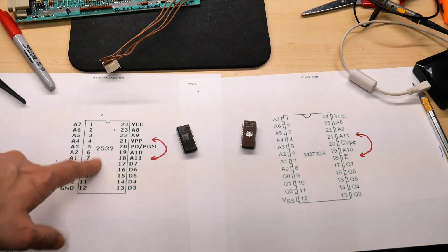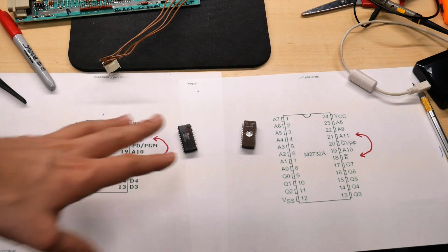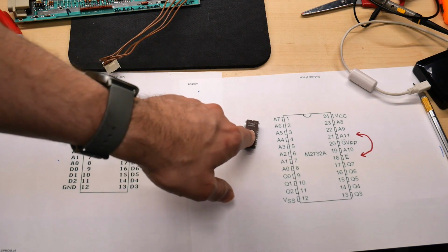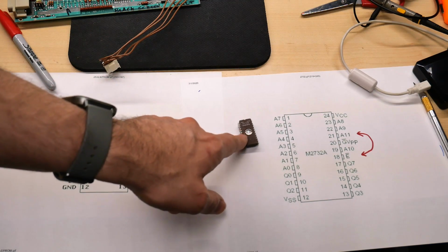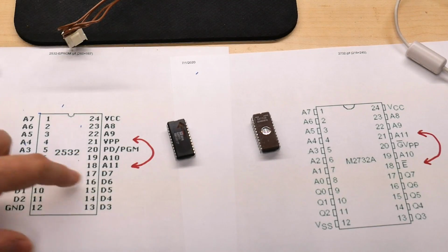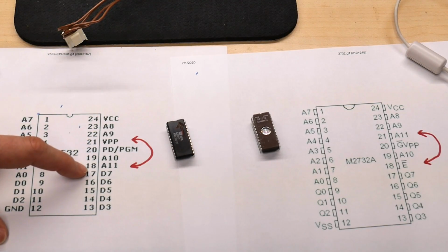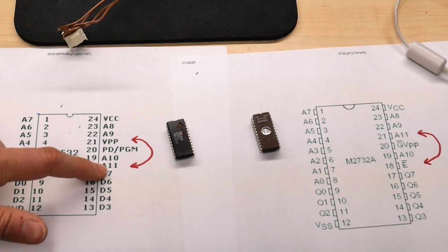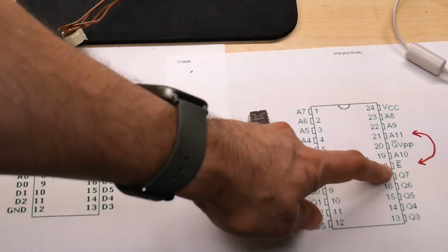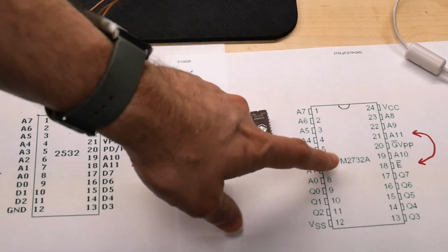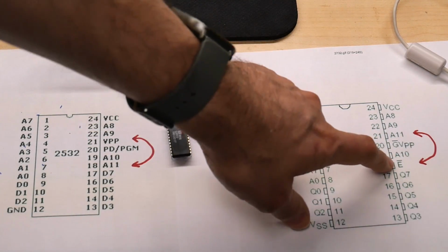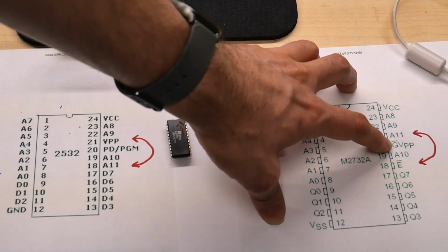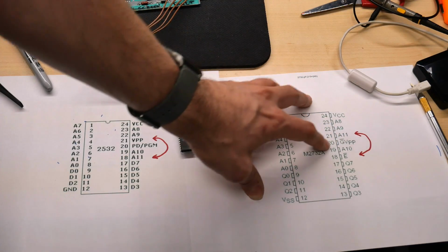If they were EEPROMs, they would be this part number, but they're a mask ROM, so of course it doesn't have that part number. And this is the pinout of the 2732, which is the EEPROM I just flashed. And when you look, the only actual difference is these two pins are swapped. 21, which is VPP on the 25, and A11 are switched around with A11 and Enable on this one. Now, when you look up the datasheet for the 2732, Enable just turns on the power to the EEPROM, and the actual chip select is this G with a line over it. Also, it's the VPP pin.